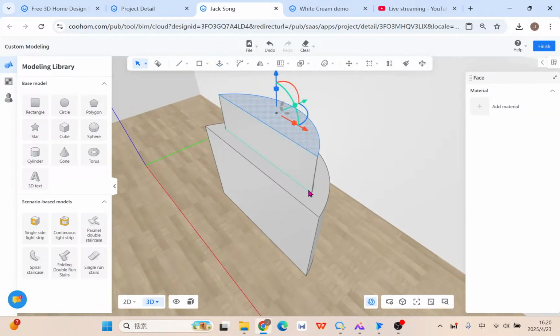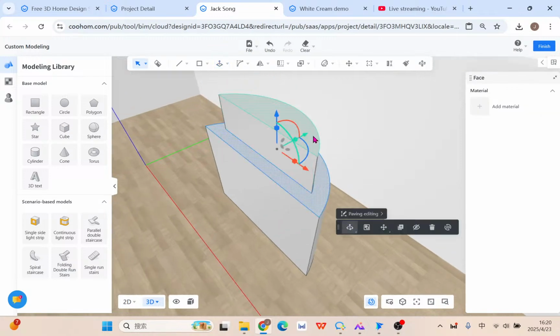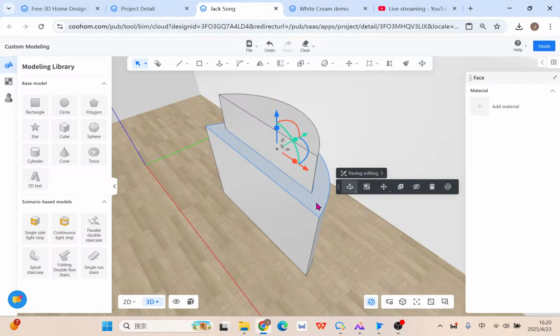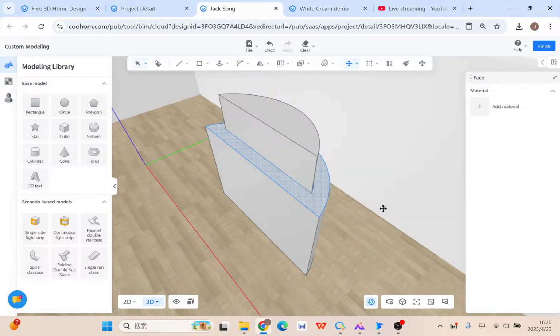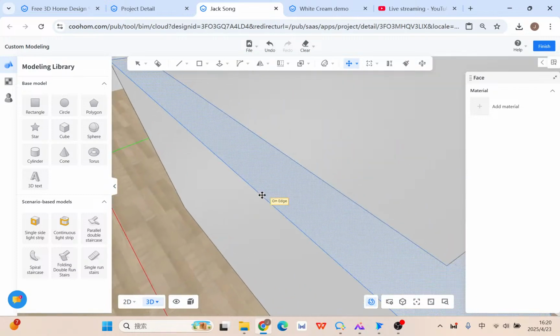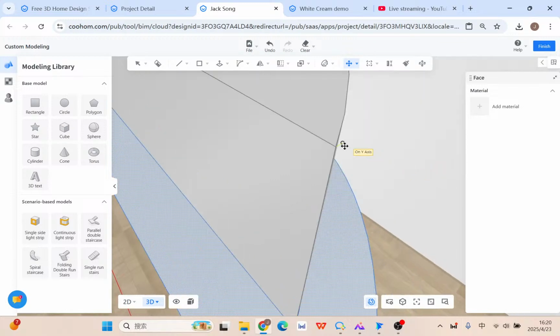And here, for example, if I don't want to duplicate, you can click and copy here. My personal preference is to use the copy rather than move, because sometimes when moving I can't directly see if it auto snaps. Sometimes when you put your mouse here it's okay for the endpoint, but still here it also shows endpoint.